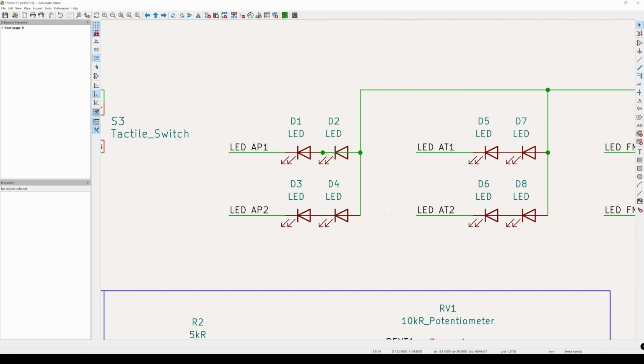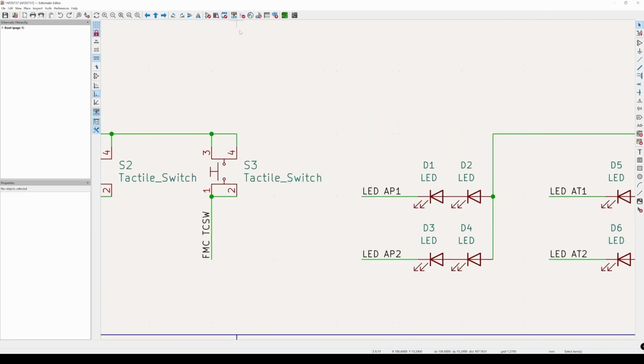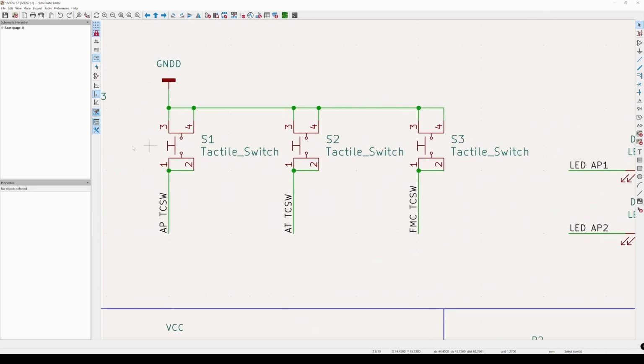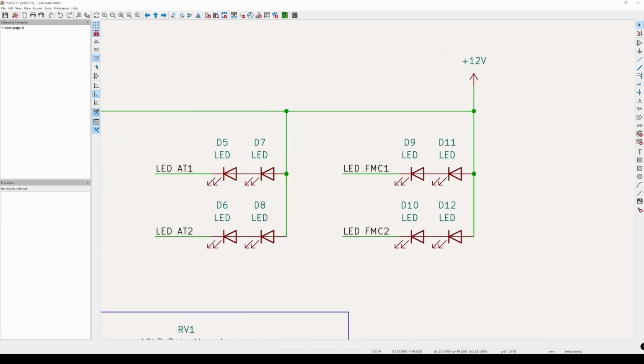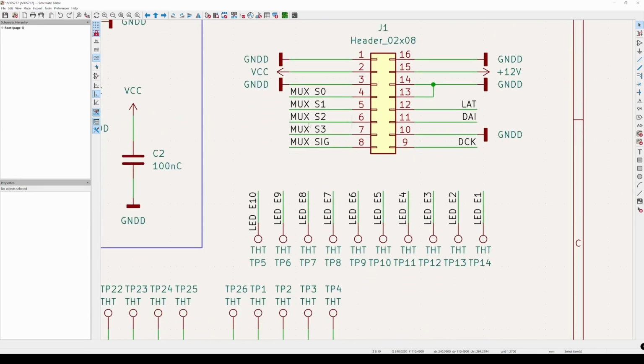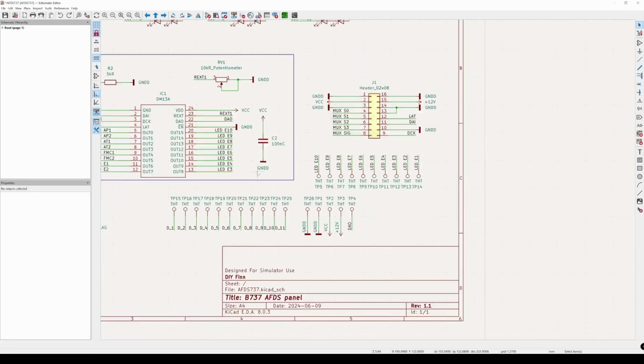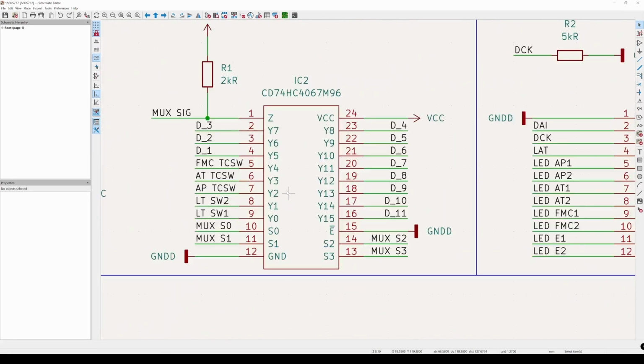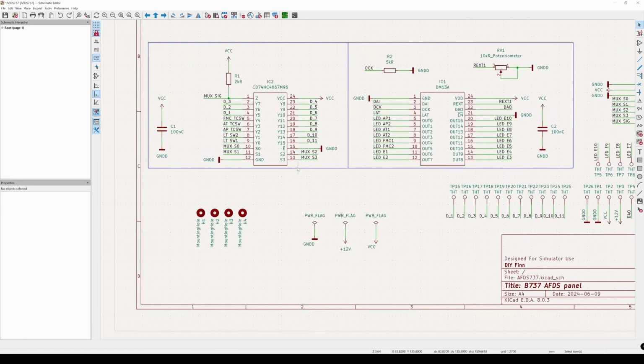These sort of mistakes would be found when you're doing the PCB layout, but always, when you're done, run the ERC and carefully check all of your connections here, especially so that you don't have any shorts, or that all of your pins are named appropriately, because these pin names are how you will start making the PCB layout, which, speaking of, is the next step.